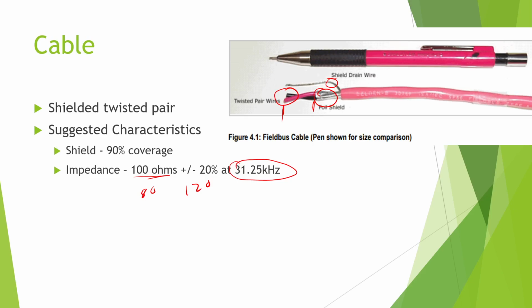You have type C wiring, which is 26 American wire gauge, and that can go up to 1,322 feet. Now this is the one that always screws with me. Type D, which is larger, 16 American wire gauge, is 660 feet. I don't know what's special about type D. I should look that up too, or my note could be wrong. I'm sticking with my note, but I'm pretty sure I pulled that right out of the reference. It's something to think about.